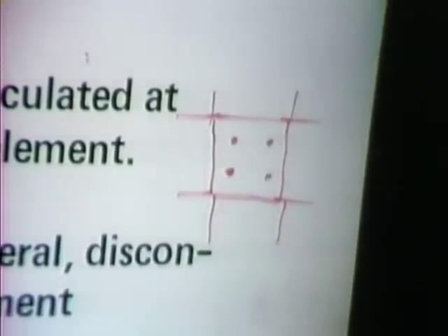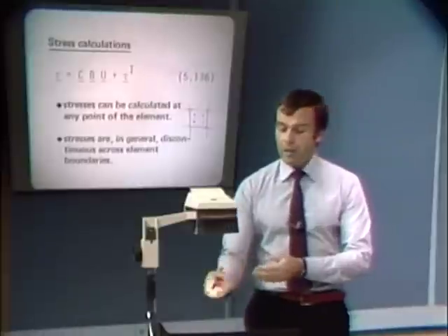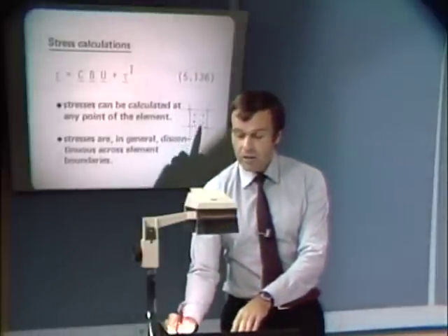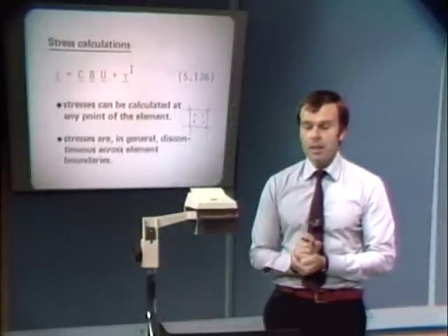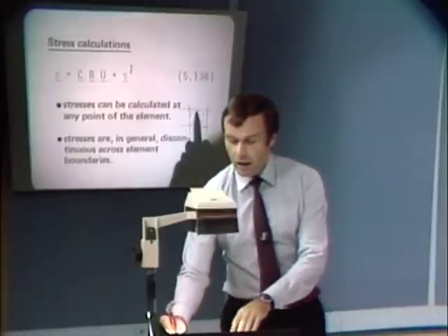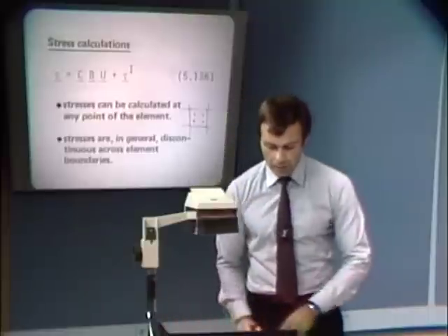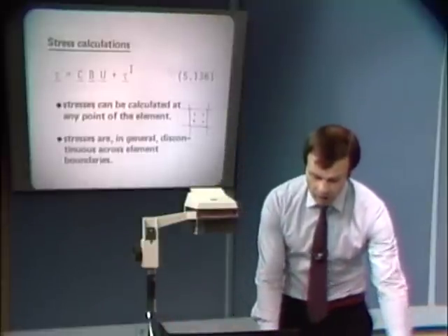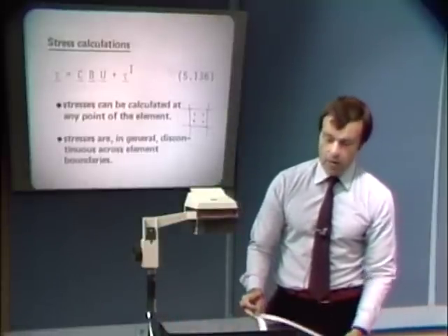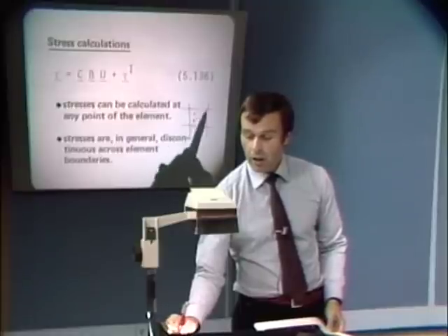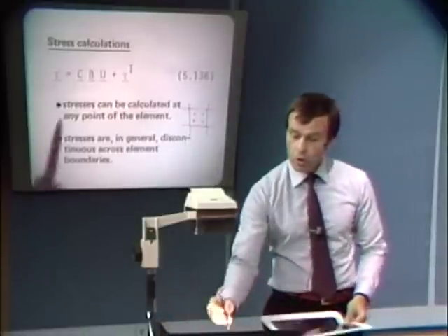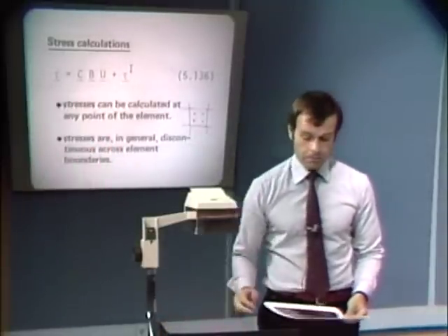I should mention here, just as a side note, that in fact one can show that the stresses at the Gauss integration points are somewhat better predicted in a finite element analysis than along the boundary of the element. So that is another reason why we predict stresses rather at the Gauss integration points and not on the boundaries of the element, using directly this approach.